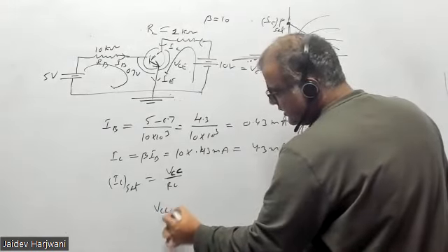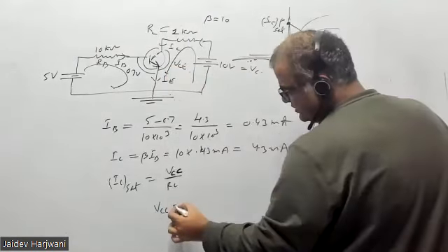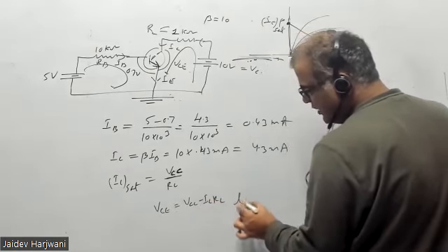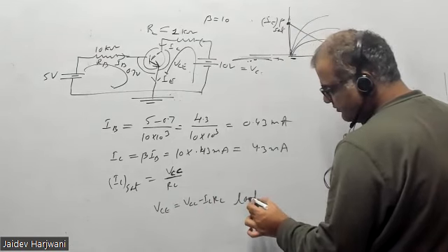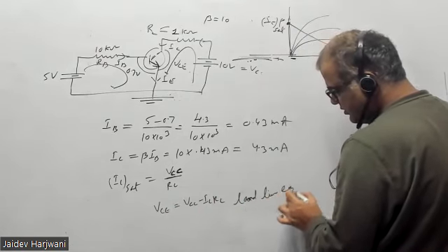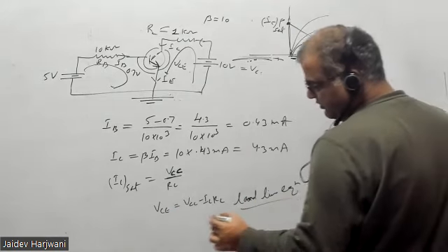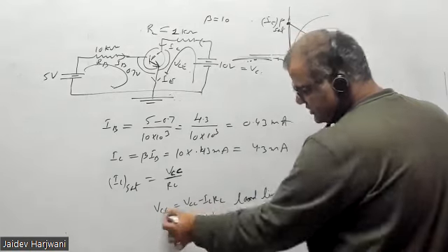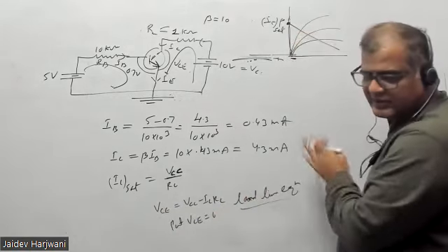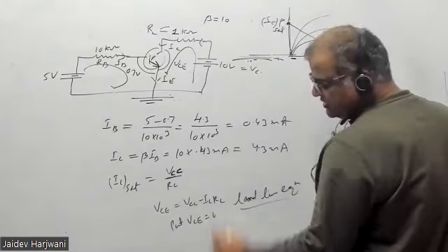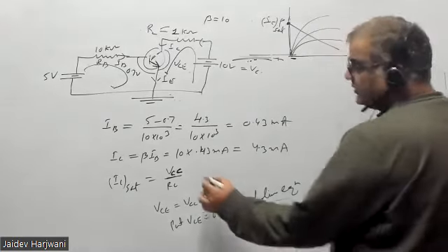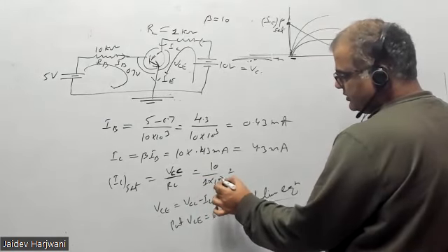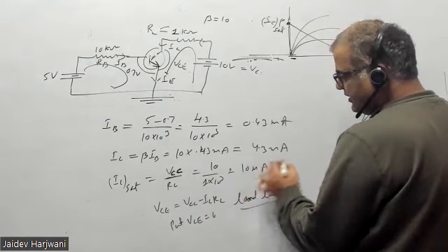I'm writing here once more. This is called the load line equation. VCE equals VCC minus ICRC. This is the DC load line equation. For saturation, put VC equals 0. The equation can be anything, here maybe many more terms we'll see later, but always you have to put VC 0. So now this will come 10 upon 1 kilo ohm, that is 10 milliampere.